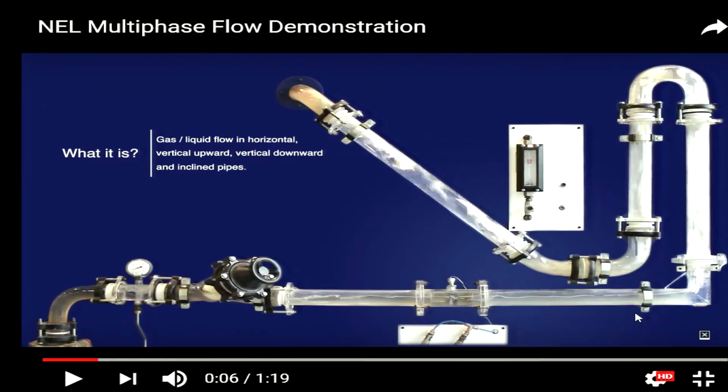But the interesting thing is that the moment it goes around a bend and goes vertical, you will see this stratified flow turn into a bubbly flow and a churn flow. What do I mean by those? I will come to that in a minute. Then it goes through a bend, and when it is a downward facing flow, you can see again it has taken a sort of mixture. One part of the pipe is in stratified flow, the other part is in bubbly flow. Then that same flow goes through at an angle, and the whole flow configuration changes.